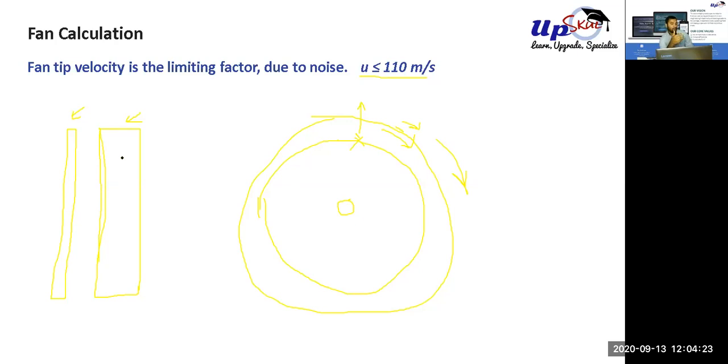For example, take very old ceiling fans, maybe 30-40 years old, the ones you see in government buildings. In our college we used to have them. Those fans have a very thick profile, so they rotate very slowly but deliver a lot of air. To do this you need more torque, so the motor was bigger. Power consumption is the same, but the torque was high.